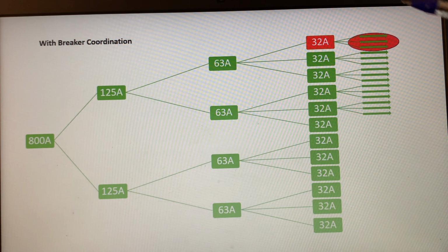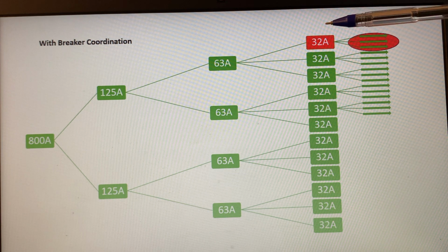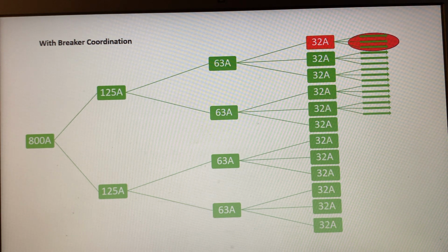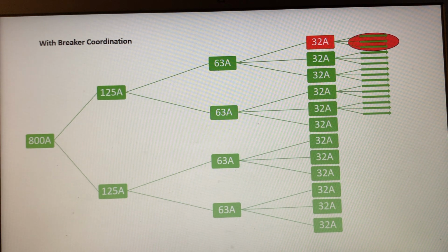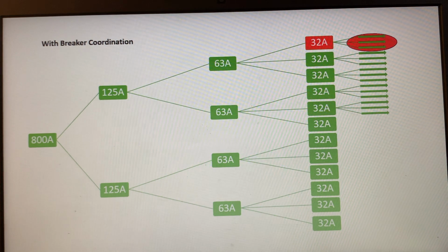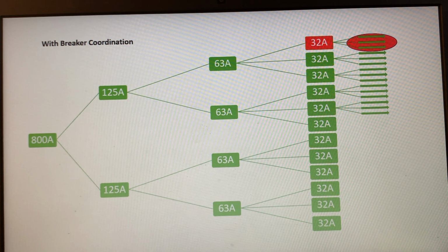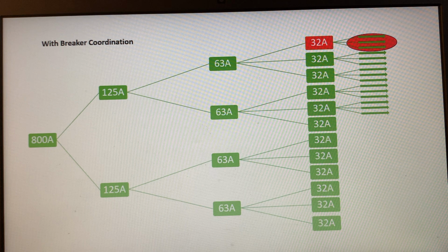One, like you have seen, is by the selection of the right combination of breakers. So, we have this breaker, we have this breaker, because of the rating itself a discrimination is achieved, because the current carrying capacity of this breaker is lesser than the other one. The other way to do this is to incorporate the settings which are available on the breaker itself, and there are two types. One is the rating of the short circuit current trip, and the other is the introduction of the time delay for the trip to take place.